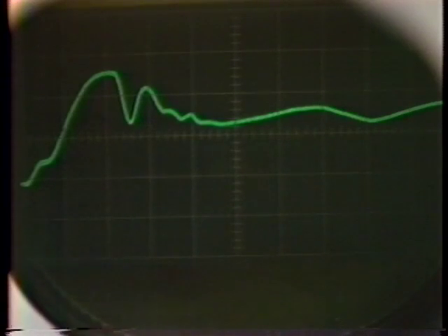I indicated that we cross over in this system at somewhere on the order of 4.5 radians per second. That's an estimate, maybe a little bit under 1 hertz. We notice that to the extent we can measure the basic frequency of oscillation, it goes maybe 5 divisions or so on the oscilloscope, roughly 1 second, so somewhere around 1 hertz. Let's get a few more traces if we can.